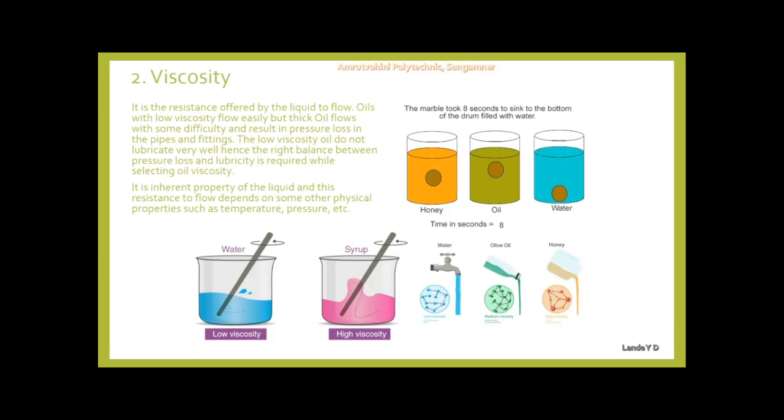To select the appropriate viscosity grade, it is important to monitor the viscosity of the oil over time and adjust as needed to maintain proper performance and efficiency. This may include regular testing of the oil and the use of additives or viscosity improvers to maintain optimal viscosity under changing operating conditions.